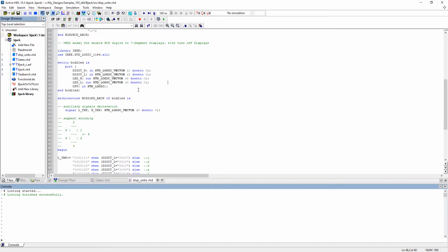Unit linting is the act of performing design rule checking on individual units or files, and can be ran in the early stages of writing your code or when applying some quick fixes. For a more comprehensive check, full linting must still be ran as it checks the full design hierarchy to catch more complicated violations, and you can learn more about that in one of my previous demonstrations. For now though, let's go ahead and get into the setup for unit linting.